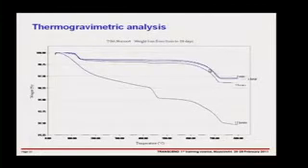And as we go on, okay, so that was 4 hours. At 4 hours, we see a little step there for calcium hydroxide, but the real difference now is at 12 hours. Now we can see this very nicely defined step that corresponds to calcium hydroxide. And we can also see a much more complex weight loss here, which is the hydrate phases. Now, what's important is to see that this weight loss for the hydrate phases starts well below 100 degrees.